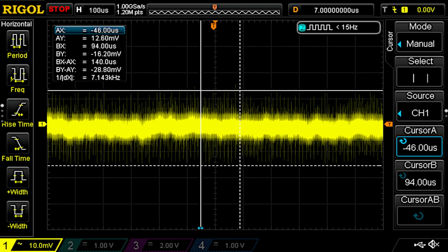This is the negative 5 volt rail. This is the only one I didn't make space for an input inductor. And it does look like some very fast spikes may be getting through. That makes me think those spikes are present and not an artifact.